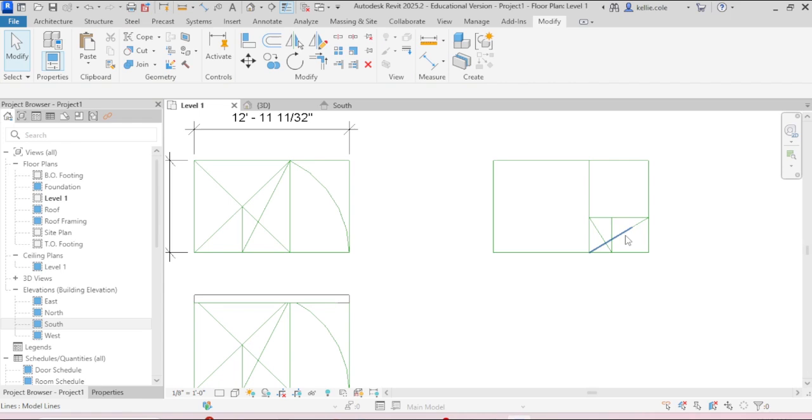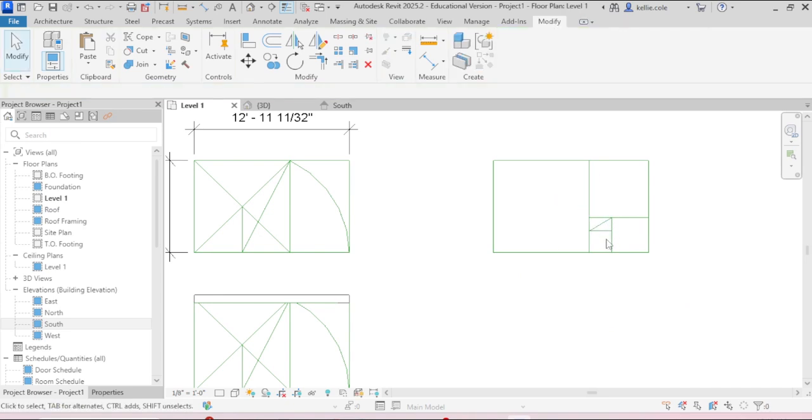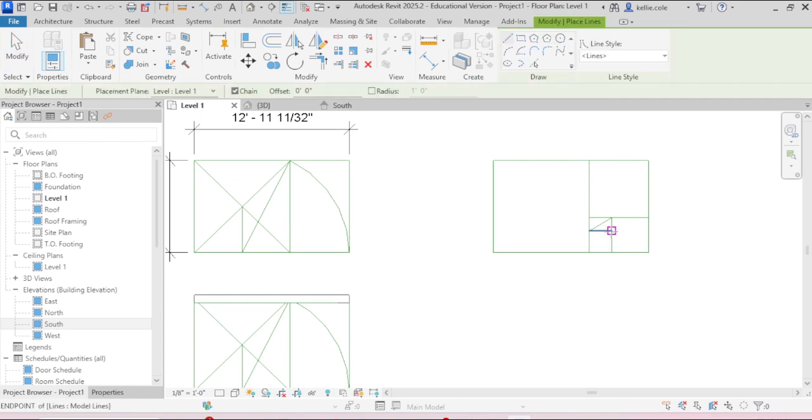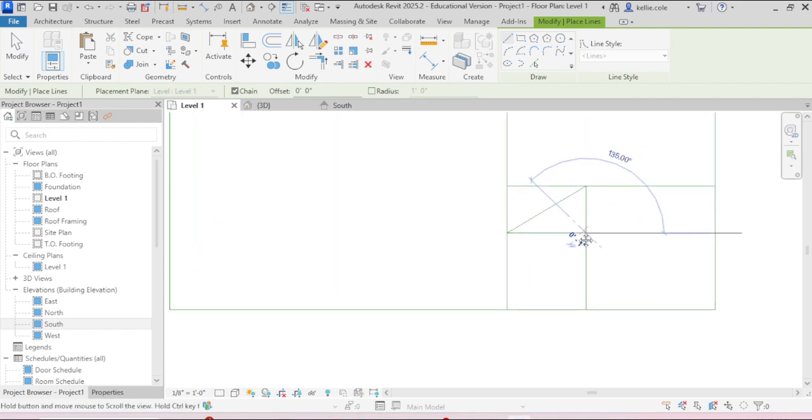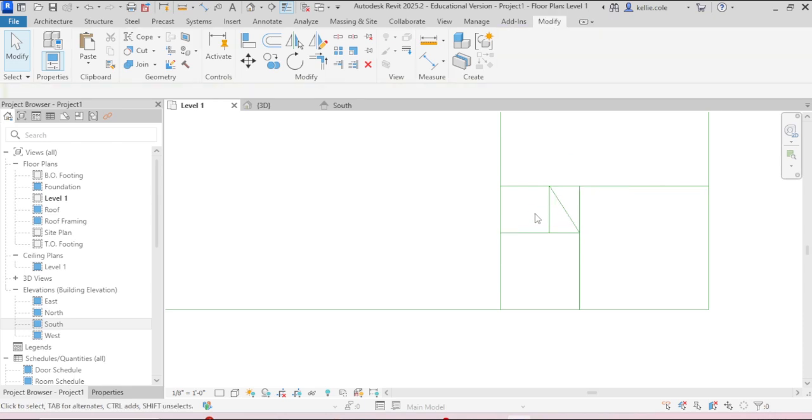Leaving the last diagonal, so we'll delete these two, we'll draw a line from this intersection through that diagonal at a perpendicular and horizontal, deleting the last diagonal. So I'm going to move into this one more time, one smaller square to rectangle, and then we'll look at the proportions and scale. So LI one last time. From an endpoint, we can zoom in, make this a little easier on ourselves. Perpendicular and down, deleting the last diagonal.